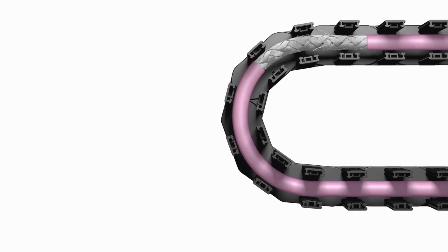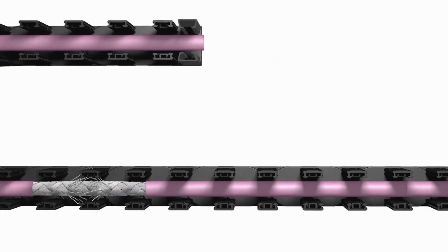What abrasion essentially does is it starts to wear at the outer jacket material, and that can cause serious issues down the line because we can get into and start digging at the conductors, which means we'd have a loss of continuity, but it could also break the shielding, which means we'd have all sorts of EMI issues and problems.